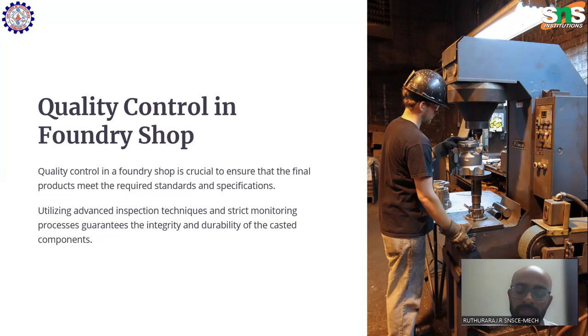One defect we already discussed is blowholes. Blowholes are caused by gas trapped inside the casting. They can be eliminated by providing vents. Another casting defect is misruns. Misruns happen because of improper removal of the pattern.